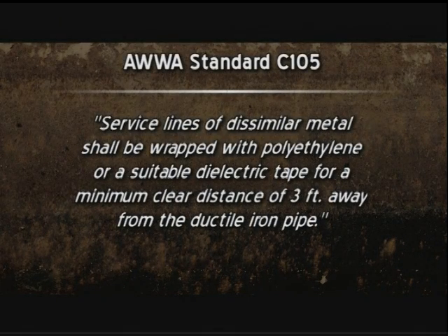And service lines of dissimilar metal should be wrapped with polyethylene or suitable dielectric tape for a minimum clear distance of 3 feet away from the ductile iron pipe.